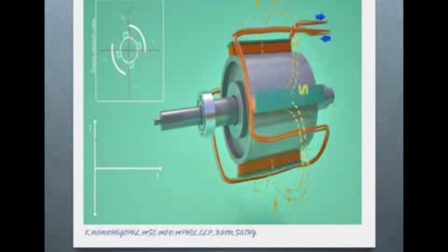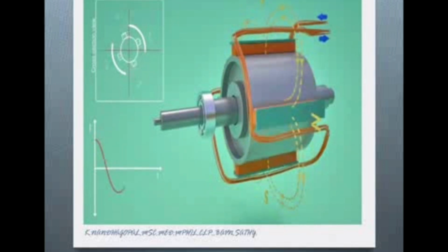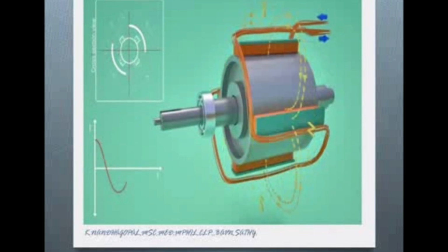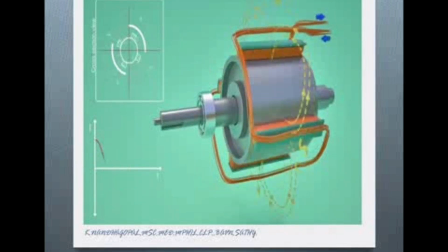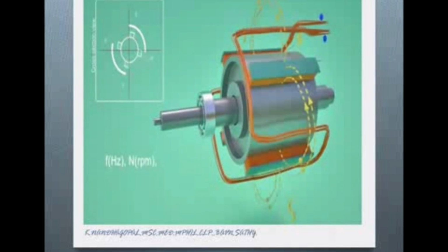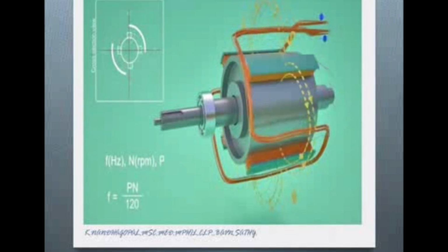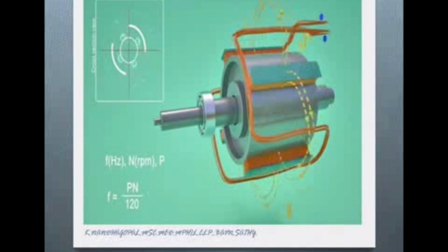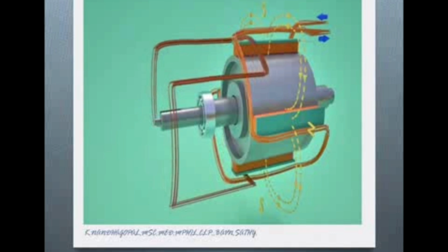It's the output current of the generator, the alternator. So the alternator produces the current like this. It's single phase, because only one current is produced by using that coil. The frequency is F equals P N by 120, where N is the number of rotations per minute.